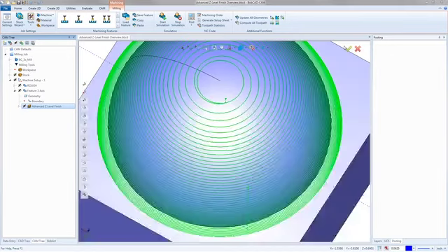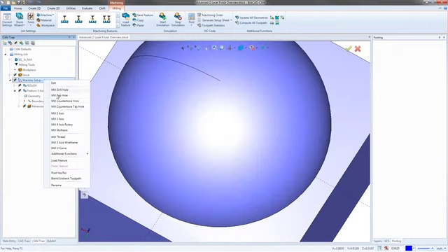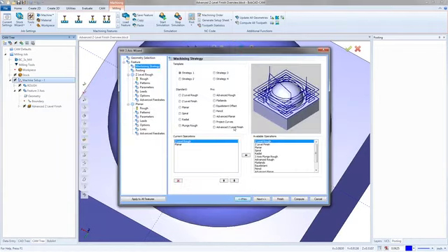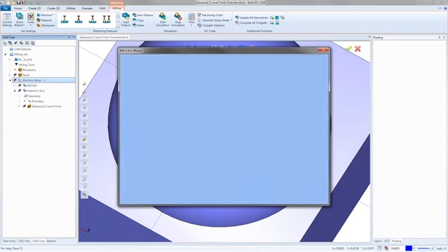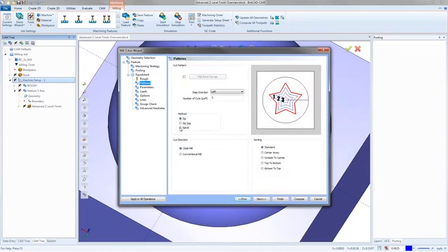You go through it when you get to the patterns page. I'm not going to do it right now, but if you get to the patterns page of the equidistant, it will also have a spiral option. So right here, I'll go patterns, and there's the spiral option.